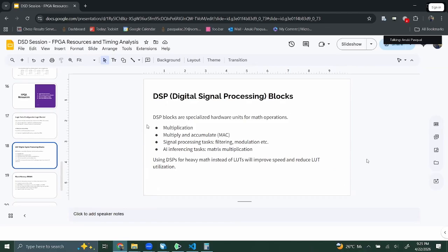But that can use a large number of logic gates, and it might be slow. Connected to our previous discussion, because it's using a lot of gates, it might have a larger propagation delay.